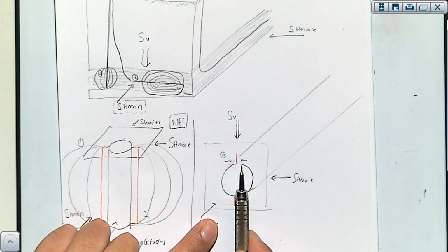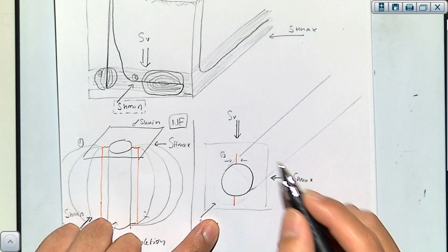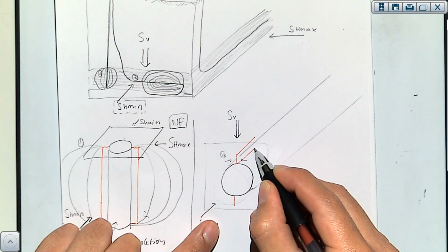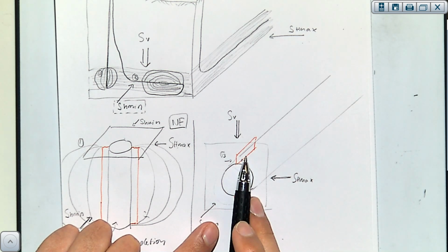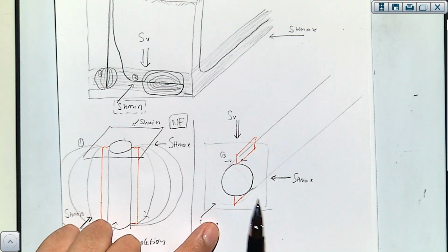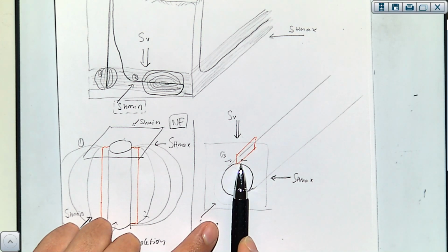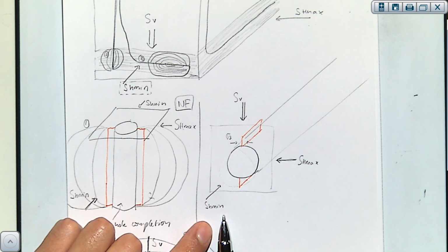Okay, if this is the case, then what this is telling me is that these short tensile fractures at the wall of the wellbore are going to grow like planes which have a strike north-south, 90 degrees, and are perpendicular to the local principal stress, which is sigma 3 in here, but it is not the far field least principal stress.